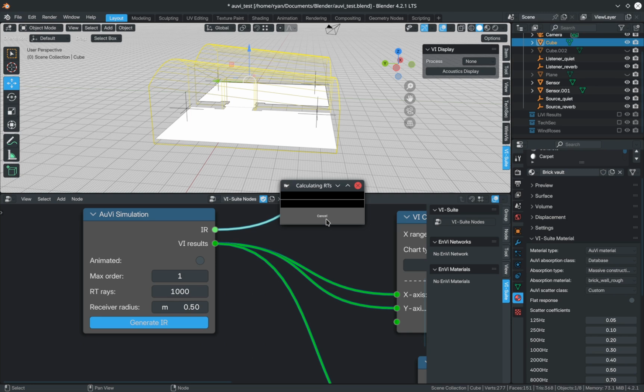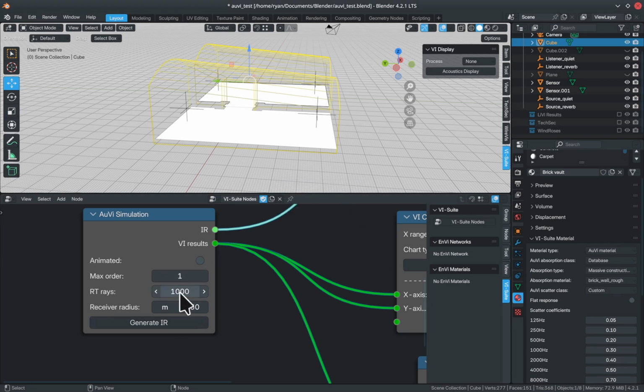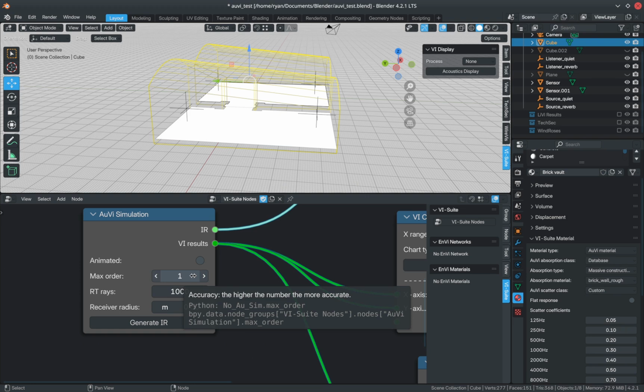And the only way you can stop the simulation is to shut down Blender and possibly forcibly have to quit Blender. So on Windows especially, these parameters are very important. If you pick, I don't know, 5 here, and you have very complex geometry, the simulation can take a very, very long time.